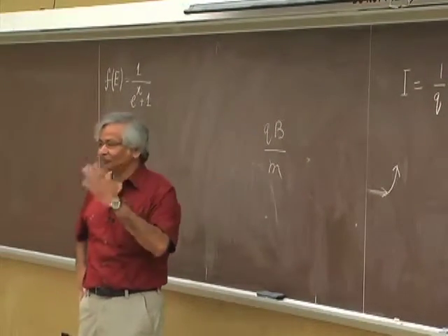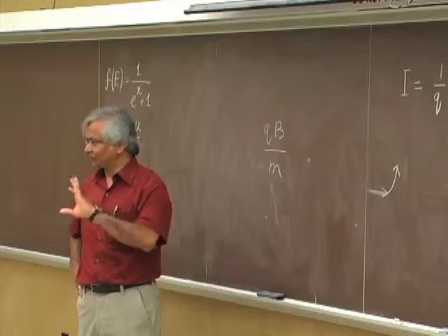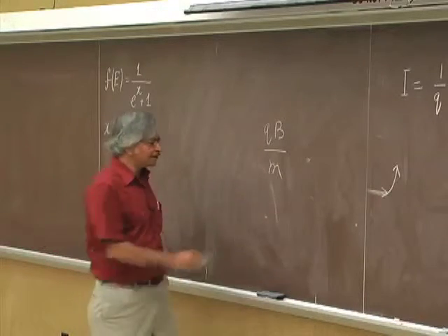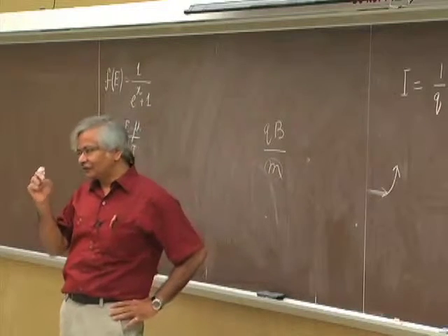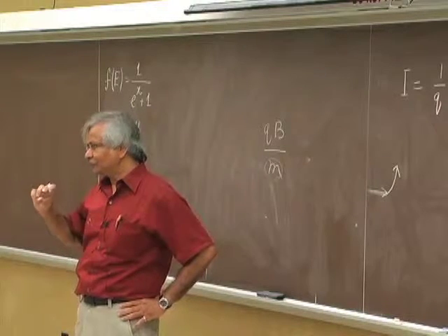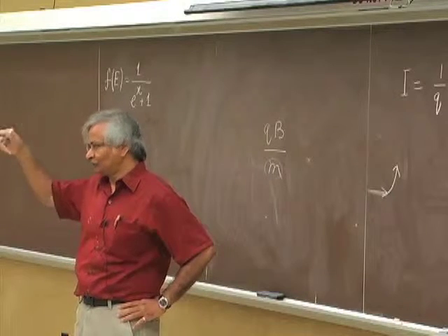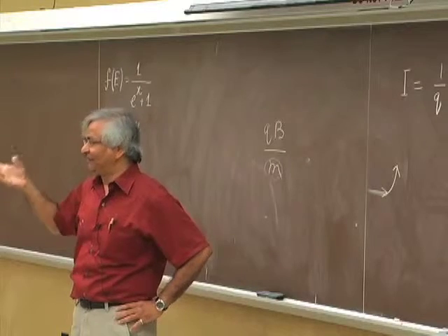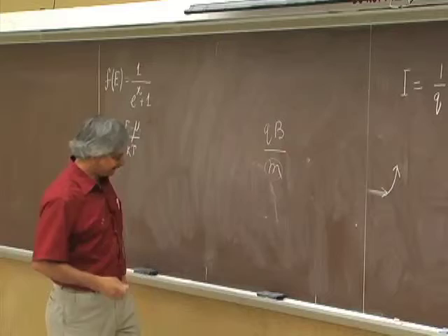What I'm saying is that what really moves inside a solid is always a negative charge, always minus Q. The reason there is a difference is because the M is different. An electron with a negative M you could conceptually convert and think of as a hole with a positive M, but you shouldn't do both. Don't make it a hole with a negative M.